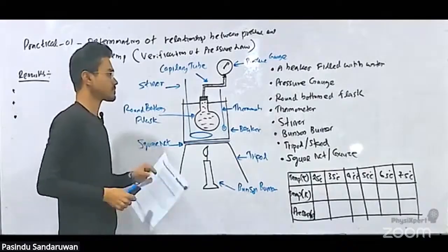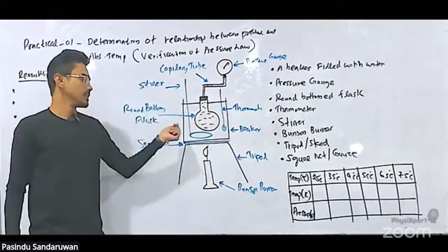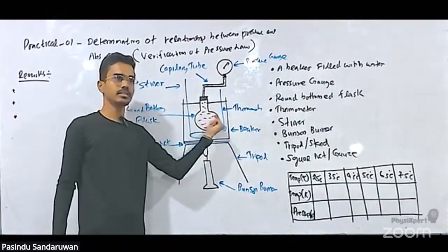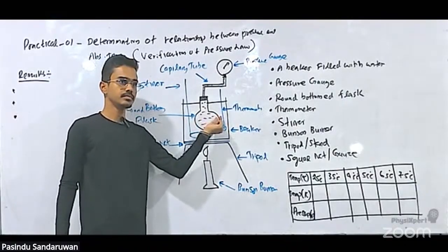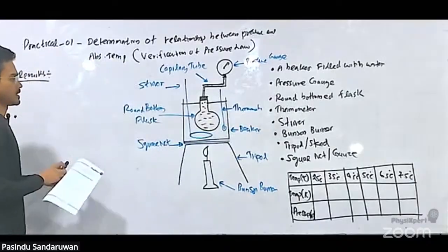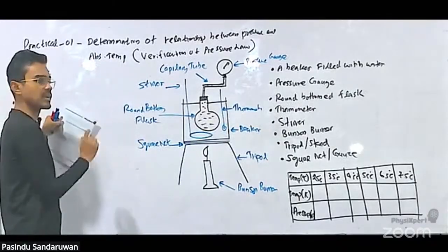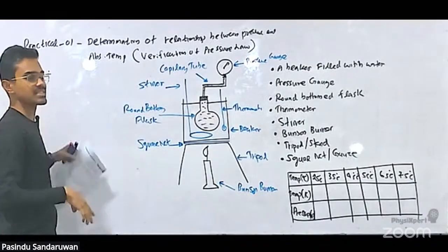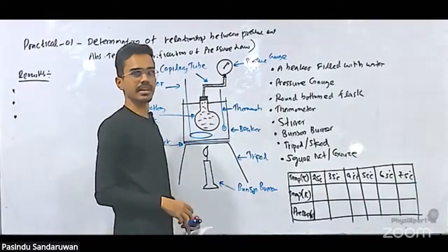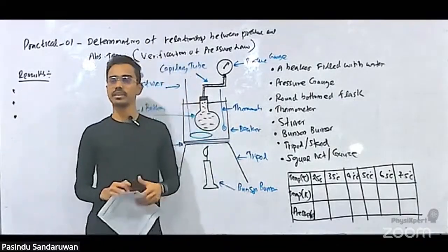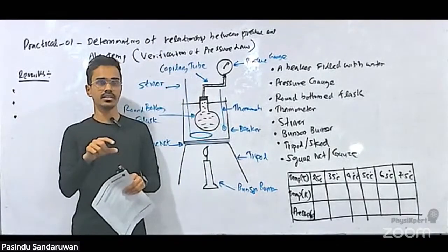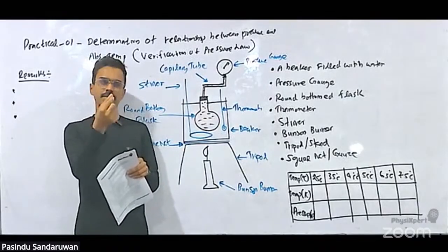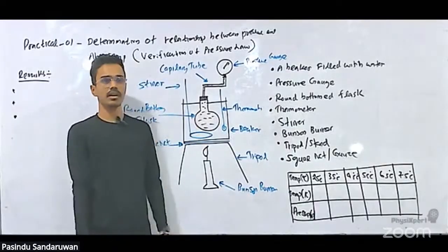Listen. Now, this is going to get heat through heat conduction through this glass, no? Then having a thin flask is very important, right? If the flask is not thin, glass is not a good heat conductor. Glass is a heat insulator, right? Then to minimize that impact, we have to have a minimum possible thickness for the flask, right?